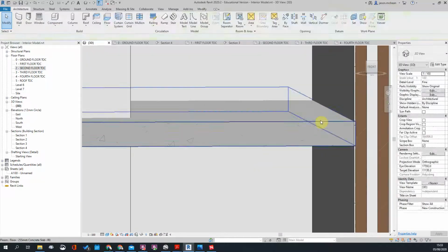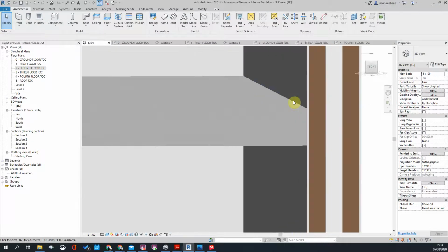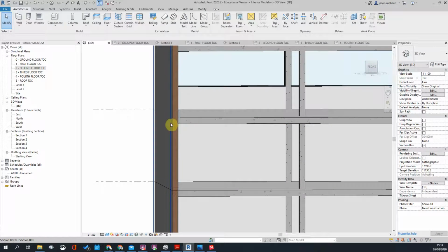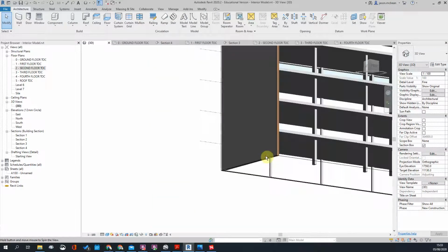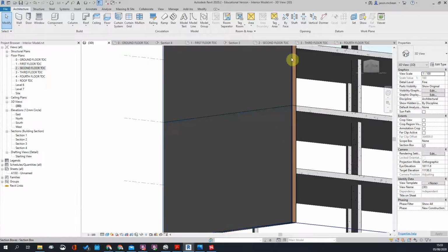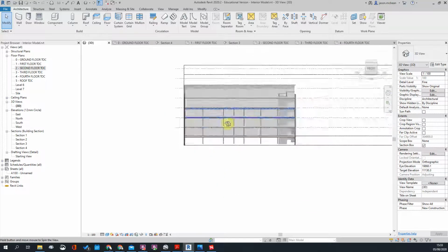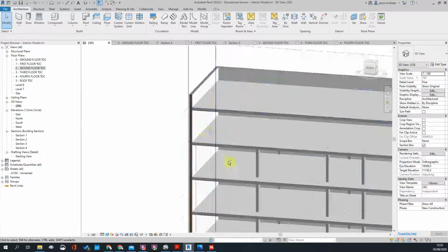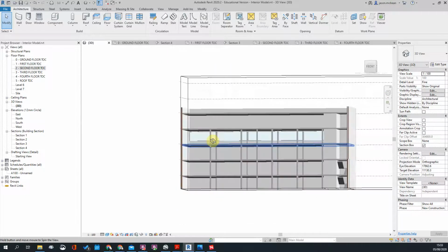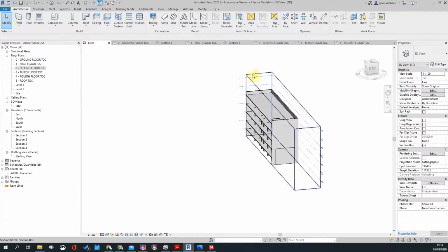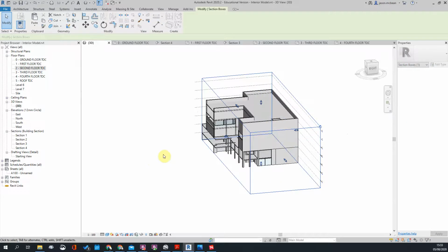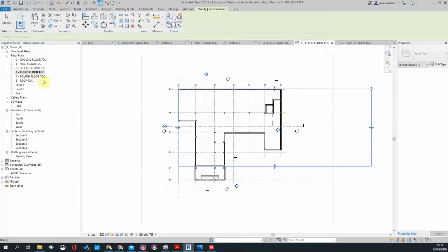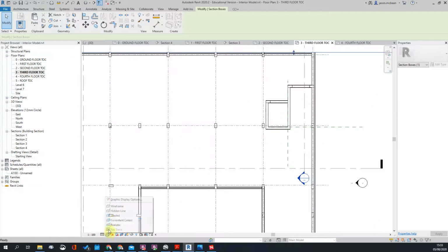I've got some good detail going, for example, and I'll show you how you can join these walls so that you get rid of the plaster line. For example, these external walls, that's good. Okay, these two walls I can join to get rid of that line, but I don't want to do that right away. These will act as a barrier, so we'll just need to make sure that the correct height, and I can use the elevation to kind of get that correct. Okay, but yeah, I'm happy with that. So now each floor, you find that I've got, so third floor, for example, I've got a slab in place.